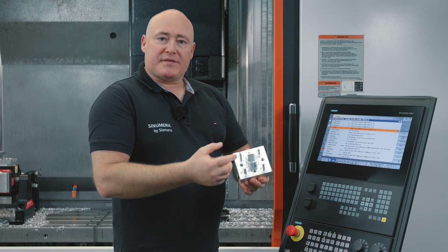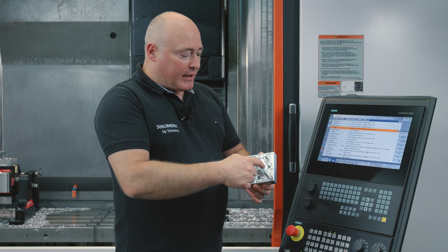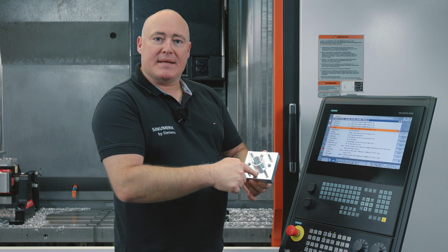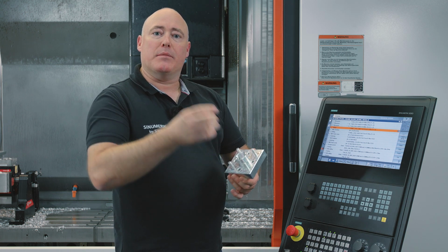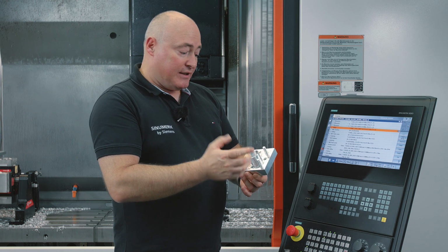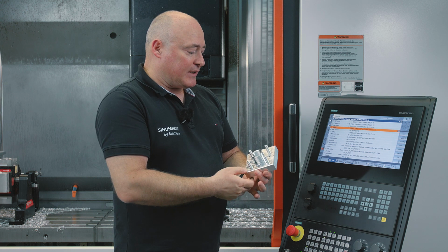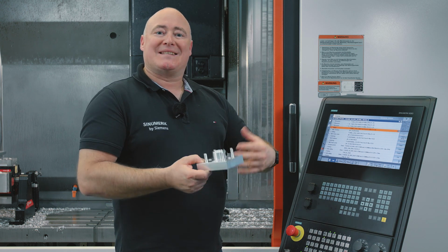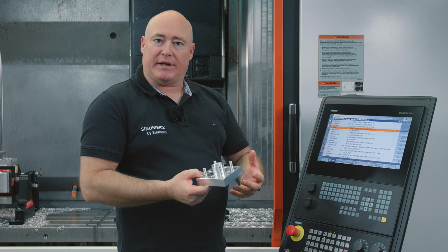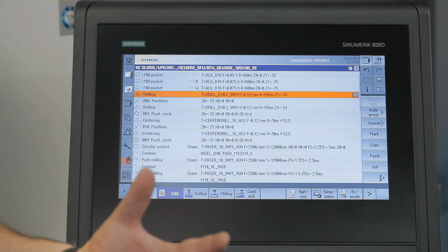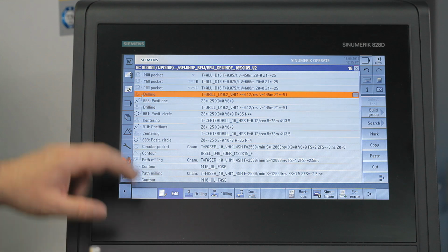And after milling, the thread tap hole diameter of our thread M12 is machined, i.e. with a twist drill. In this case, a solid metal twist drill that goes through the material in one pass and generates a diameter of 10.2 mm. M12 minus 1.75, tap hole diameter for M12, 10.2.